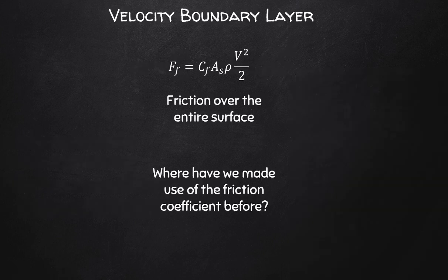Note also that the friction coefficient discussed in the heat transfer textbook is exactly the same as the one that we have been using in our piping systems design, this F prime. Okay, so we have frictional pressure drops through pipelines, and we calculate F prime. And so this Cf is the same. It is the frictional coefficient. The textbook just uses the notation Cf, where the piping systems book just uses the notation F prime.